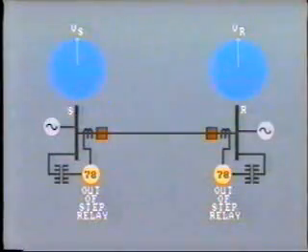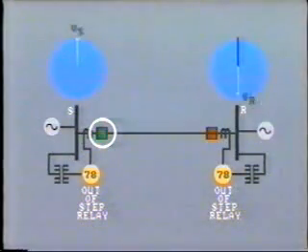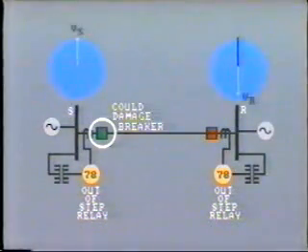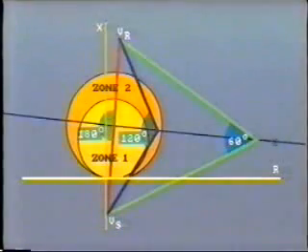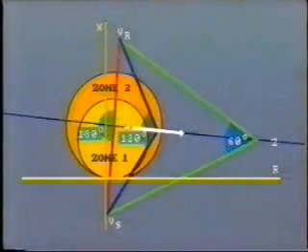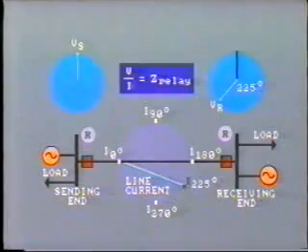Where the out-of-step relay is used to instigate tripping, the timing of the breaker opening is most important. If the breaker is opened at the precise moment where the two voltages are 180 degrees apart, then an exceedingly high voltage will exist across the breaker contacts, and this could cause breaker damage. For this reason, when the out-of-step relay detects the out-of-step condition, it will delay tripping until the measured impedance starts increasing again. That is, moving through the first zone and out into the second zone again.